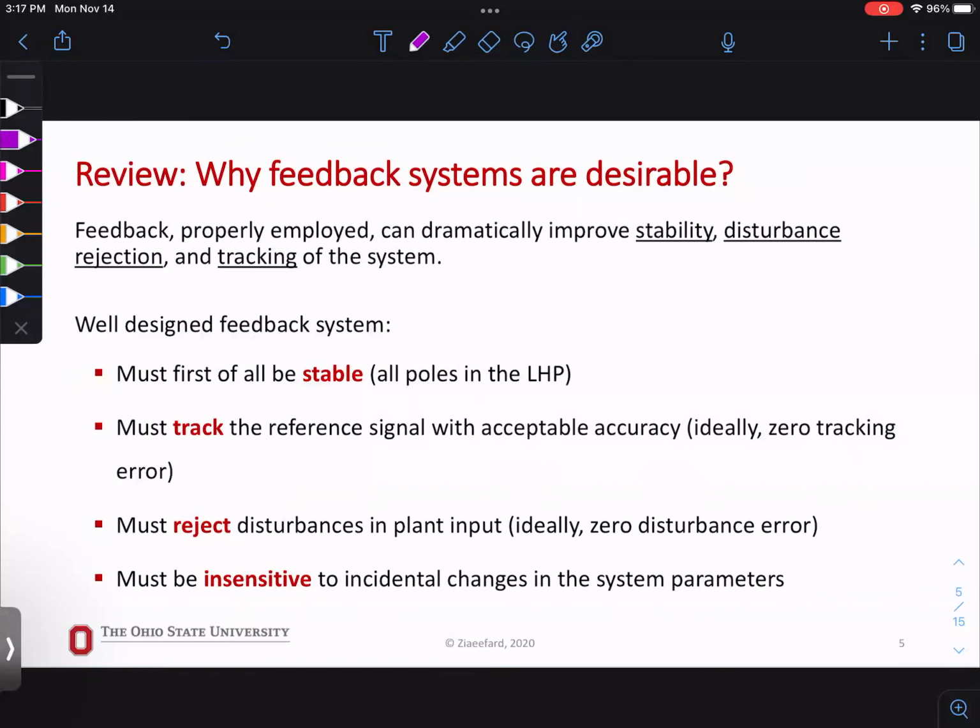All right. Now, we also want our system to be stable. Mathematically speaking, you can think of it as keeping all the poles in the left-hand side. So when I say mathematically, I mean in terms of control. If you remember, poles come from setting the denominator of the transfer function of your system equal to 0, and then finding all of those s values. Those are your poles. We want them all in the left-hand side, making sure that our system always reaches some steady state.